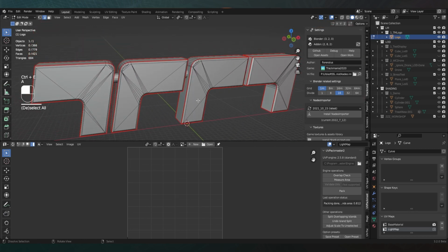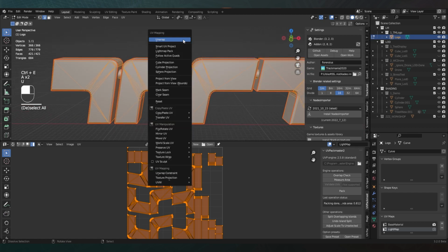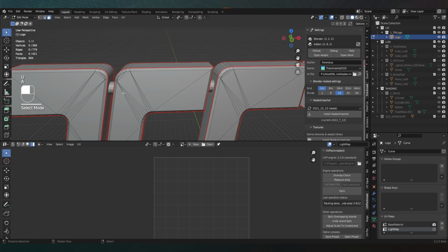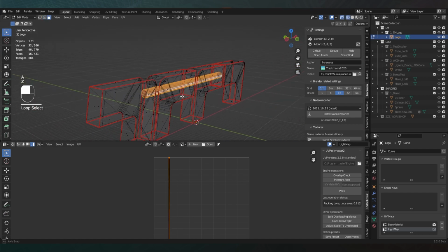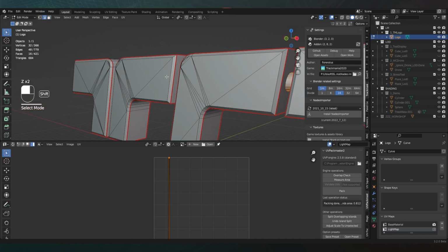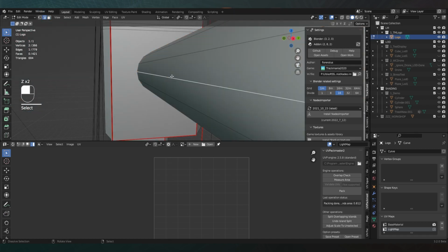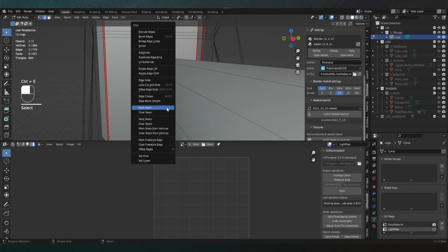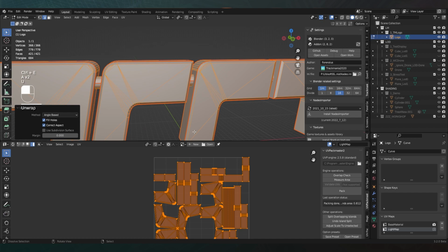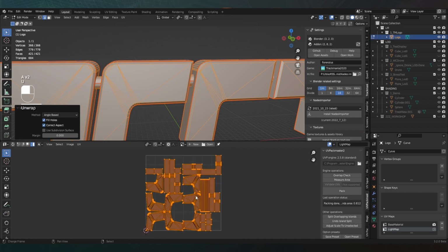Okay. So unwrap it, and something is broken. And I know what is broken. We got this little cylinder here. And of course, this one needs to be unwrapped as well. And usually for cylinders, just mark one edge, select one edge, and then mark it as seam. And we can try it, and we will have a proper light map. So basically, that's the way it works.